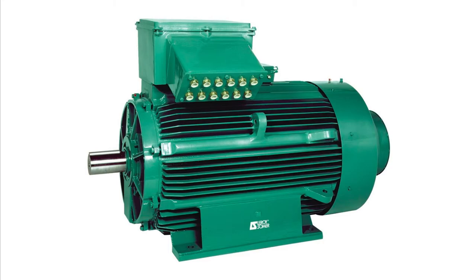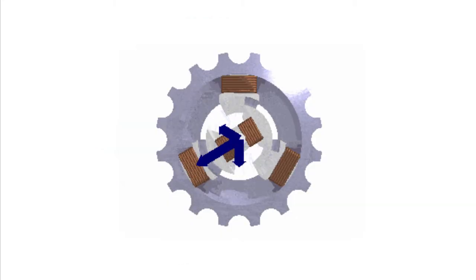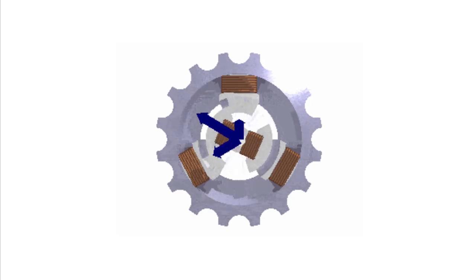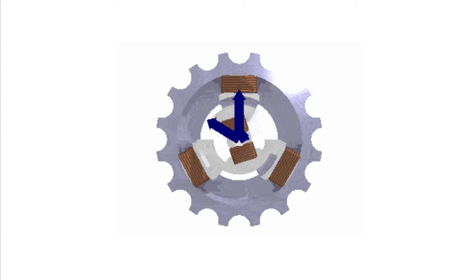Each one has two main parts: the rotor in the center that spins, and the stator, which is on the outside and is stationary. For a synchronous motor, the rotor is the part that turns the shaft. It is usually lined with permanent magnets that get attracted to or repelled by the stator. The stator is a non-moving shell, and it has electromagnets that move the rotor. AC current is put through the coils, which in turn makes them act as bar magnets to attract and repel the rotor. The phase is shifted so that the magnetic field will turn in a circle, which then attracts the rotor.